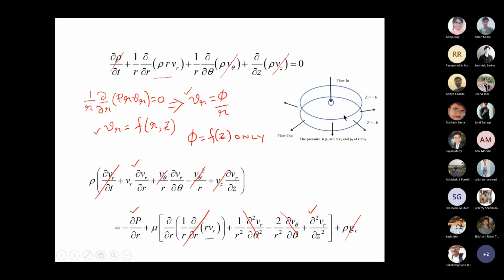But the gap is so small in those microscale systems that the gradient, and therefore the viscous transport of momentum, will still be substantial. So the pressure drop required to make a liquid flow through a small conduit is going to be phenomenally larger as compared to the pressure gradient necessary to make liquid flow through a macro scale system.